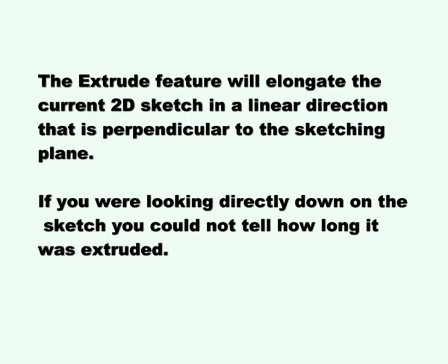This video will cover the extrude boss and extrude cut features. The extrude feature will elongate the current 2D sketch in a linear direction that is perpendicular to the sketching plane. If you were looking directly down on the sketch, you could not tell how long it was extruded.